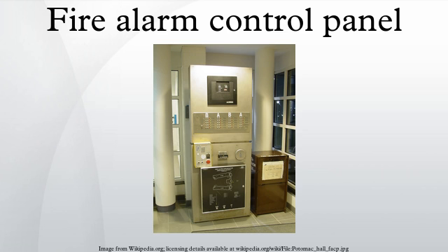Drill, also known as manual evacuation, or evacuate. On panels that have this function, the drill function activates the system's notification appliances, often for purposes of conducting a fire drill. Using the drill function, an alarm is normally not transmitted to the fire department or monitoring center. However, building personnel often notify these agencies in advance in case an alarm is inadvertently transmitted.